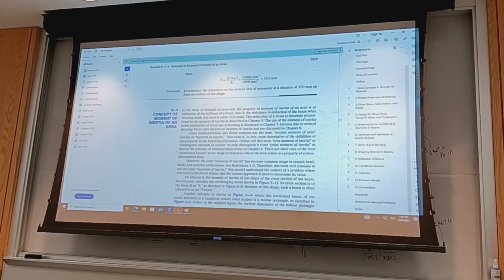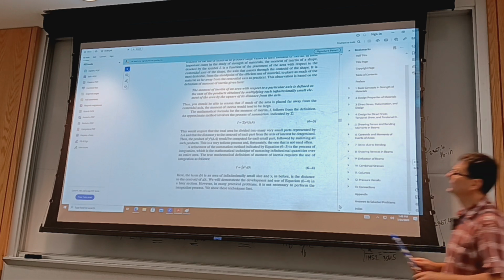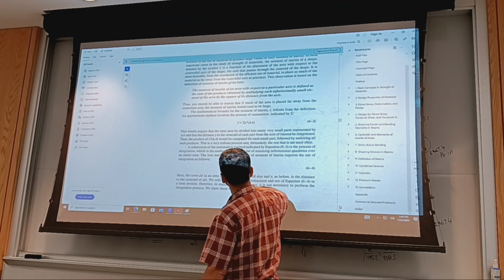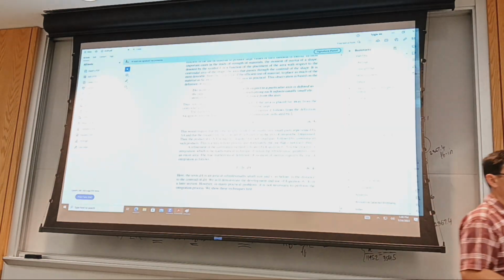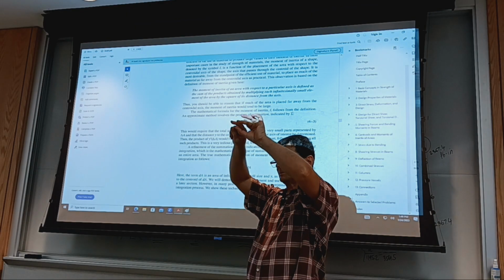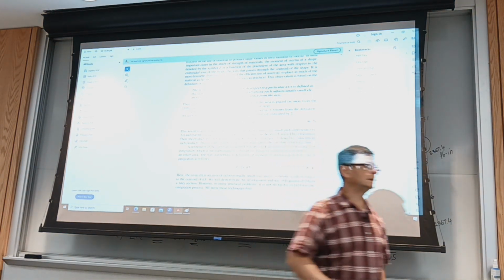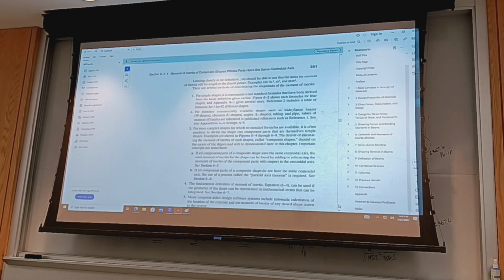Now, moment of inertia of area. It's an integral, and in general, the moment of inertia about an axis is the integral of the distance from that axis squared times the small, infinitesimal piece of area. And in statics, you took either stripes and moved along the y-axis, or sometimes you took little rings where you increased the radius, but their thickness was dr, maybe.